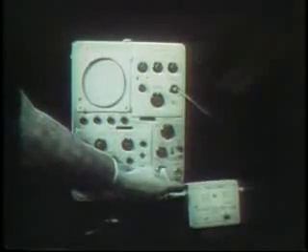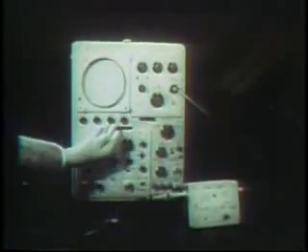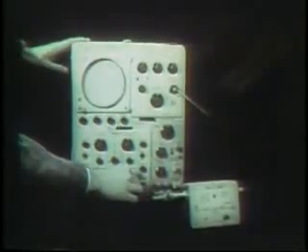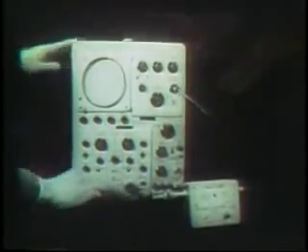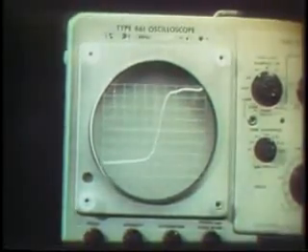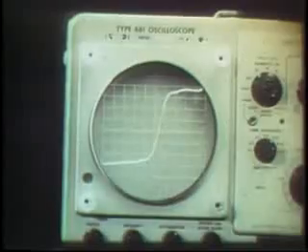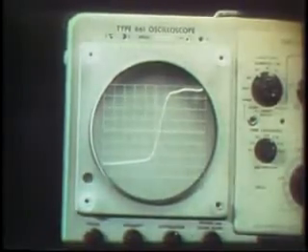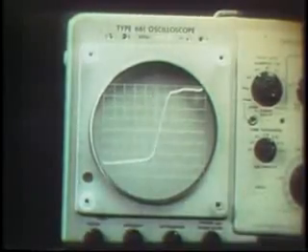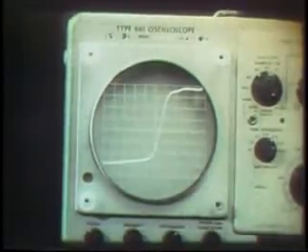By connecting the signal from this generator into this scope and pushing the scope to its maximum speed, we get this display. The rise time of the waveform you are now viewing is less than 1/4 of a billionth of a second. This means there are harmonics present which extend up close to 1.5 billion cycles per second.